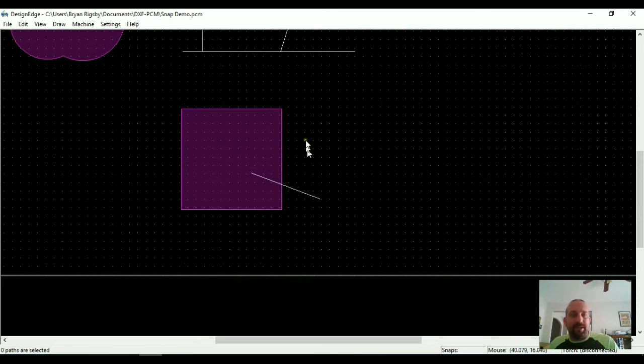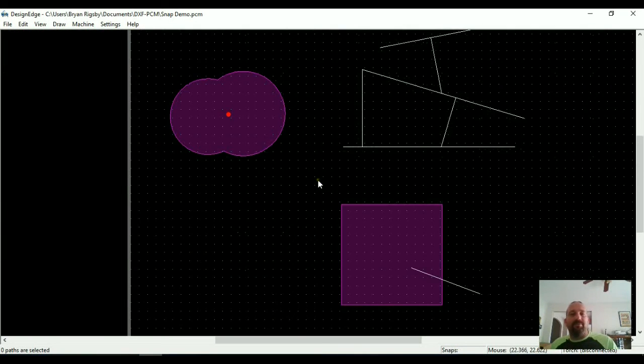We didn't look at the intersection snap. It's pretty self-explanatory. Line, I intersection snap, and if I click on this square here, it jumps down to where that line intersects it. It jumps to the nearest intersection. So most of this I've done in drawing, but snaps do accurately work for moving and other editing pieces that you want to do.